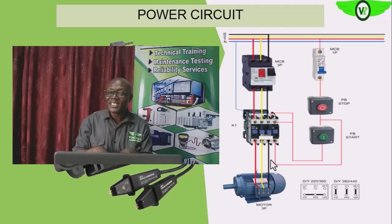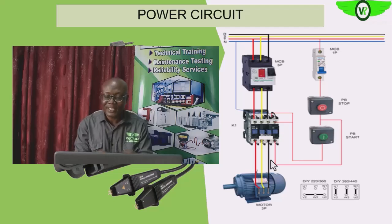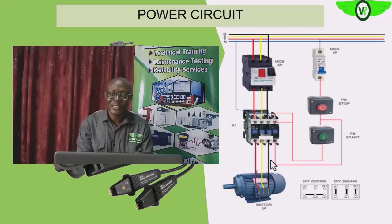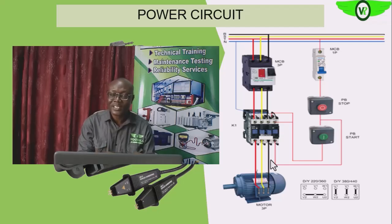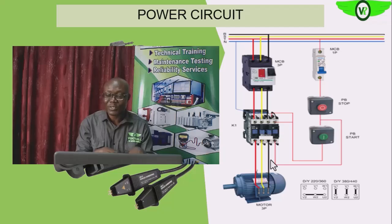But if the unbalance is coming from within the electric motor, we need to check further. We can do the winding inductance test to ascertain the level of unbalance in the inductance. Remember, the inductance will give us a better value than the low resistance meter, simply because resistance has a linear relationship, or a direct relationship, with the number of turns.